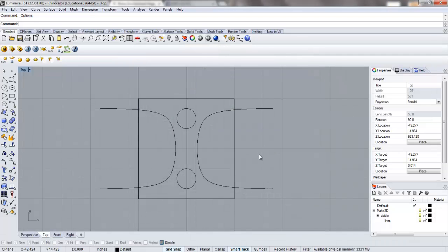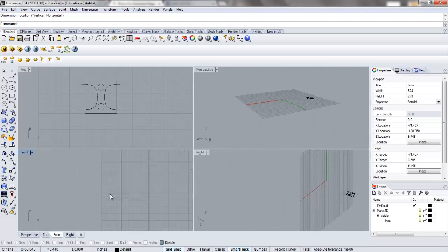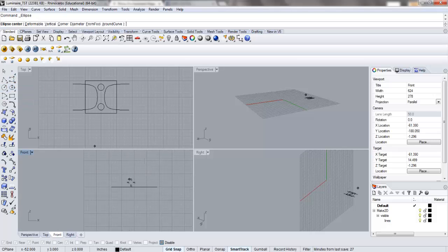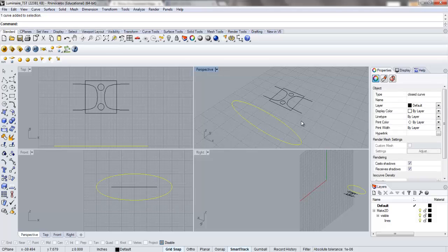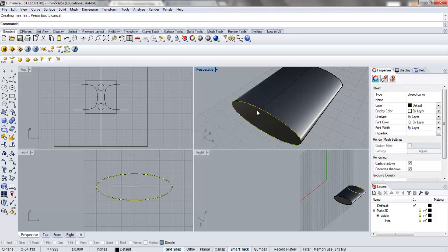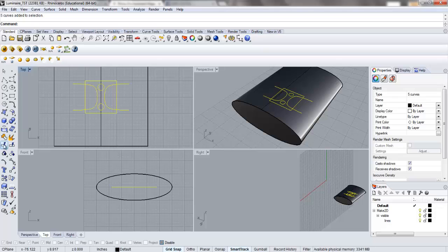And I'm not going to scale this because I want this to remain at 10 by 10 because I'm going to scale it down. So now we know that we're in inches. And so I'm drawing that in plan, and I'm going to make this pretty basic here. We come over here and I'll go ahead and make this that thickness. So we're going to now just generate a series of extrusions. So I'll just extrude this curve. And then I will take this guy and I'm going to go ahead and trim out our actual tile.